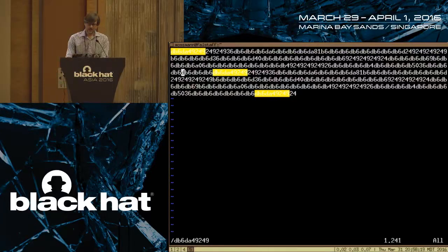Now, how far into this? If I look at my counter at the bottom right, 250 characters in, I get a repetition, and then the next one here is at 499 characters in, right? So I have a consistent repetition every 249 characters. So I'm seeing that what Yardstick 1 is detecting as one packet is really multiple repeated packets.